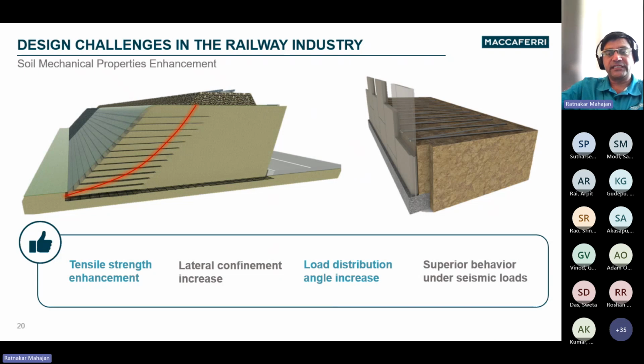The geogrid provides resistance with an additional tension to the entire embankment. In fact, thanks to its high stiffness, especially when compared to the rigidity of the ground, it absorbs the tensile stresses without excessive deformation. This results in improvement in mechanical characteristics of the soil that guarantee the stability, that is global stability, local stability.